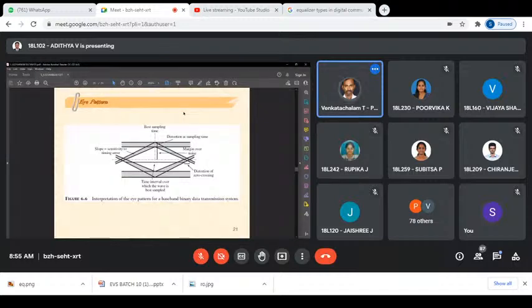When you look at the eye pattern, it is almost like a superimposed triangular waveform. The time instant at the peak is the best, optimal sampling time, the time interval over which the wave is best to sample.